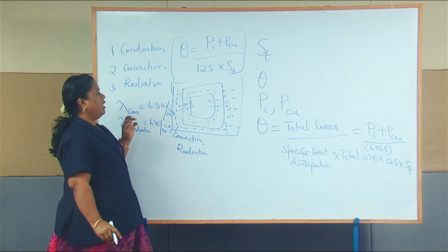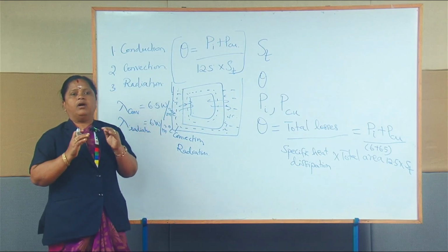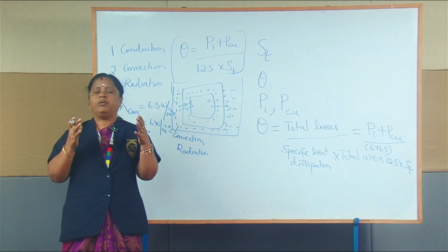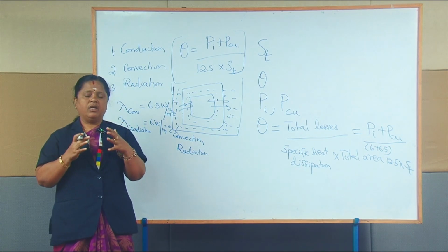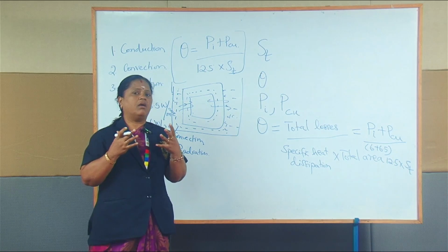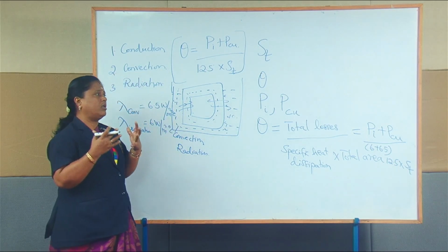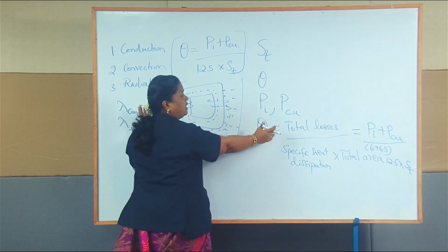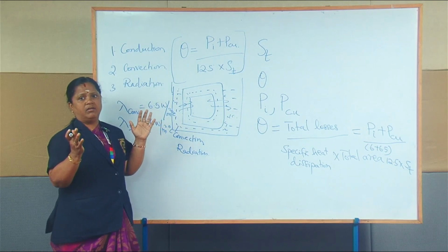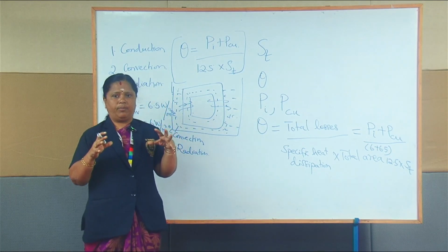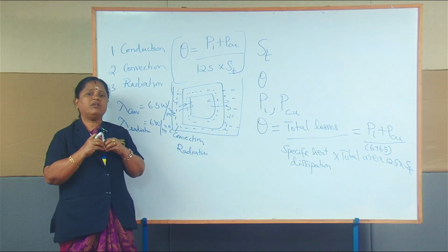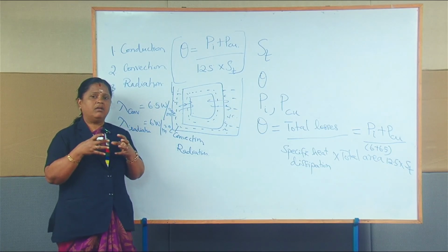Okay. So, now if the power rating of the transformer is huge, then definitely the loss will be huge, right? In order to dissipate this heat loss, either we have to increase the size of the tank, in order to increase the volume of the oil. Now, there will be a space constraint, right?